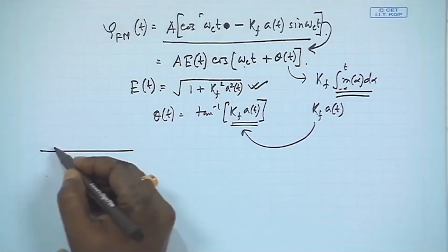Okay. So, the first task when I am generating FM, because I know whatever the frequency variation is, keeping that intact, can I make this amplitude constant? That is the first thing, because that should be the way FM is modulated. Okay. So, whenever I do FM modulation, amplitude must not vary with time. Here we have a variation. So, we should somehow employ some circuitry which keeps that amplitude fixed, while it will not touch the phase, which will remain the same. What is the process of doing that? So, whatever amplitude variation we have, suppose an FM modulated signal might look like this.